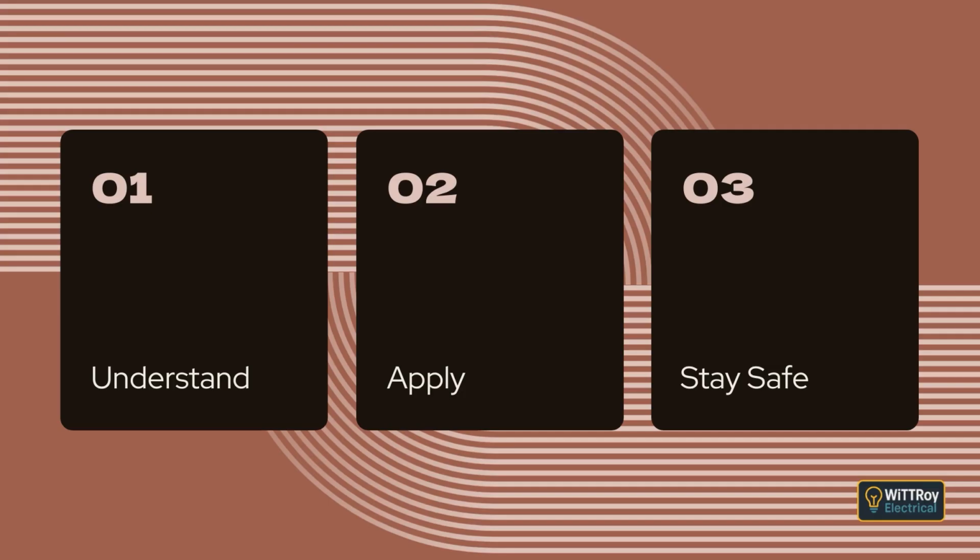Clause 3.10.3.5 Passage for conductors. When cables pass through metalwork such as tubes, channels, conduit ends, or openings, they must be protected. If the opening is bushed, the bush must be securely fixed. If it is not bushed, the edges must be smooth with no sharp projections that could damage the insulation or sheath. Clause 3.10.3.6 Terminations. Wiring enclosures must terminate and be supported so that cables passing into equipment are fully protected.